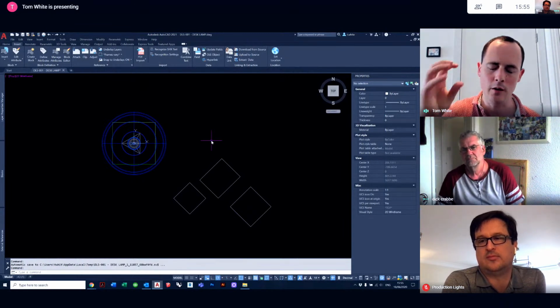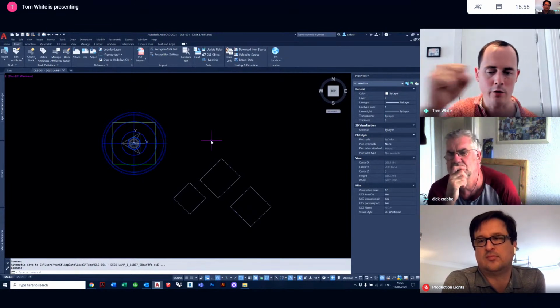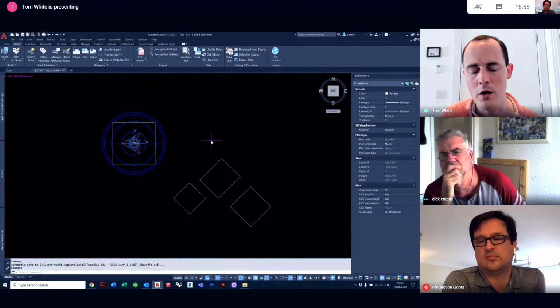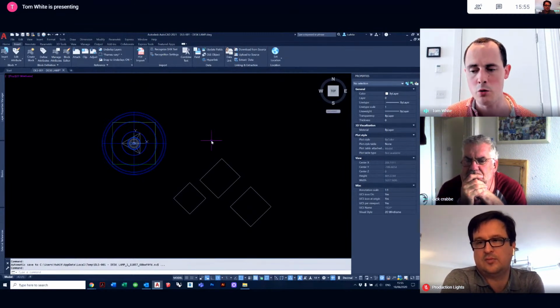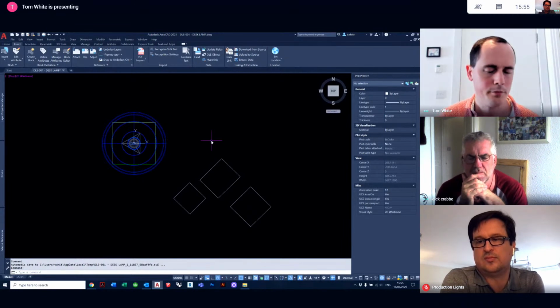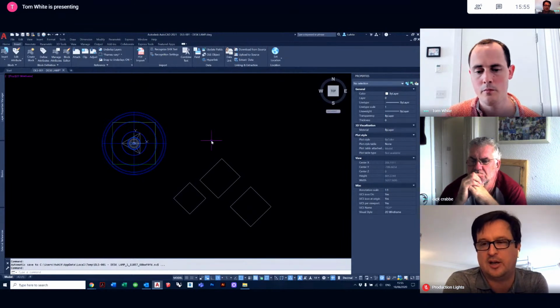So when you bring an XREF into AutoCAD, try your best never to move that physical XREF around the drawing. Go back to the person who produced the drawing originally and ask them to adjust their drawing for future revisions. Gotcha.